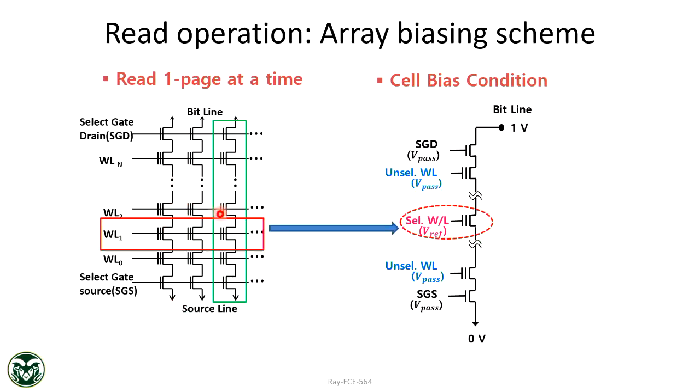Change the state. Yeah, there will be a lot of disturb, right? Because when you're reading this word line 1, the unselected word line can get disturbed. We are putting high voltages. So suppose you have a USB drive and you are reading only one song again and again, which means other songs will be corrupted, not the song you are reading. You see what I'm saying?